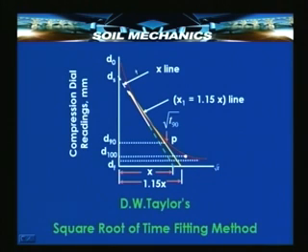What we do is we find out the actual starting point of this curve, because the original dial gauge reading may be D0, but there is a certain amount of seating requirement. That is, when you apply the load initially the pore gases get compressed and expelled, and therefore, the actual time at which the hydrodynamic phenomenon starts can be taken as corresponding to the dial gauge reading ds. So, ds for all practical purposes is the initial dial gauge reading, and that is the straight line part of the u versus root t curve.